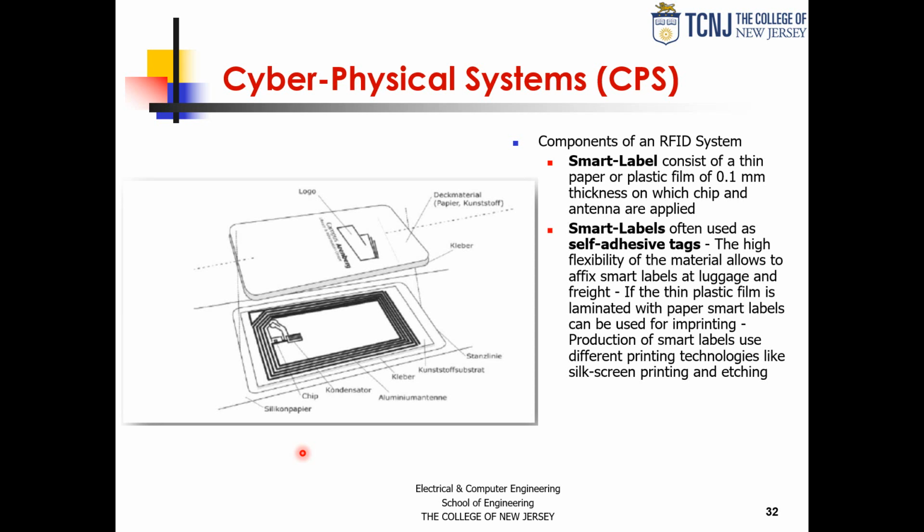Then you put the metal with the absent photoresist in acid, and everything that is not covered by the photoresist goes away, and then you get these metal patterns on the label. Very similar to what is done for chip processing, same thing.